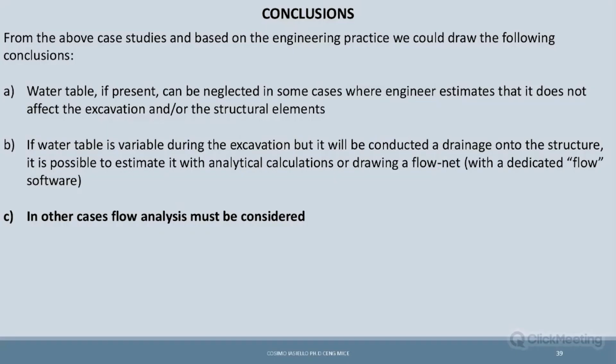So the conclusions from what I showed you, and if you want, we can go through the models. The water table, if present, can be neglected in some cases where the engineer estimates that it does not affect the excavation and or the structural elements. This can be done in some cases.